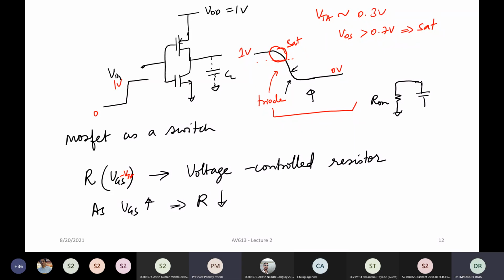Sir, but if we are using CMOS as a switch, then we usually tend to have the gain as high as possible, making the switch as ideal as possible. So the transients should not exist in a switch, sir. Okay, so that is in the ideal world, right? But you don't have any switch in the world which has zero on resistance. So you are partially right. There will be some transient. Oh, yes, it will always have a transient.